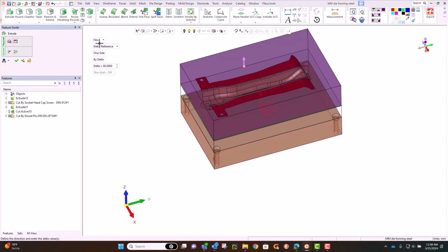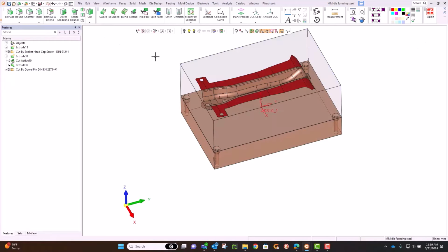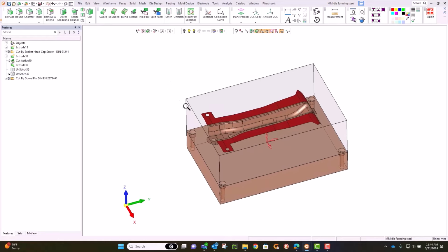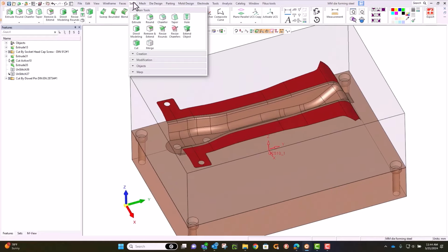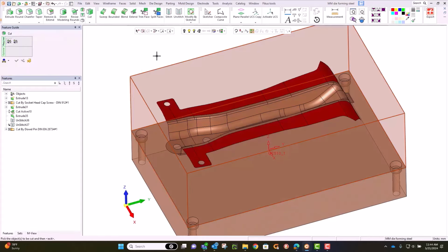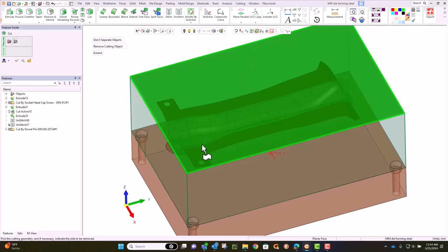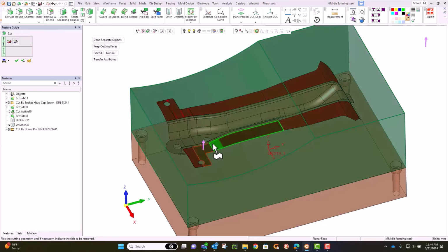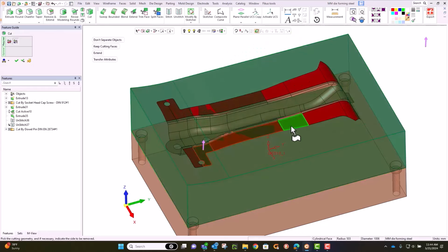Here we're working again with solids, parametrics, but we have a hybrid environment that allows us to work as a full object volume or as an individual sheet. So I'm just going through patiently, picking each one of these flange surfaces, and you can see how it's changing the shape of that die steel.